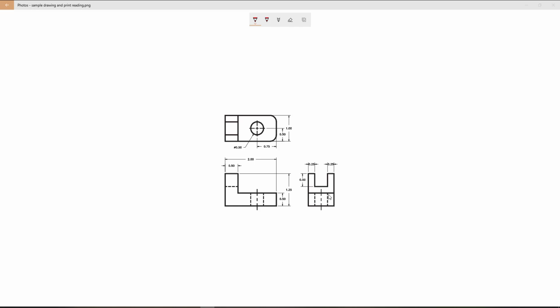Now, architectural drawings have primary views also. They've got floor plans and elevations. Same concept. The floor plan is looking down from the top. Elevations are looking from each of the sides associated with that floor plan. So they have the same context overall. Whether it's a shape drawing like this or an architectural drawing, they all work similarly in that concept of relationship between the drawing views.